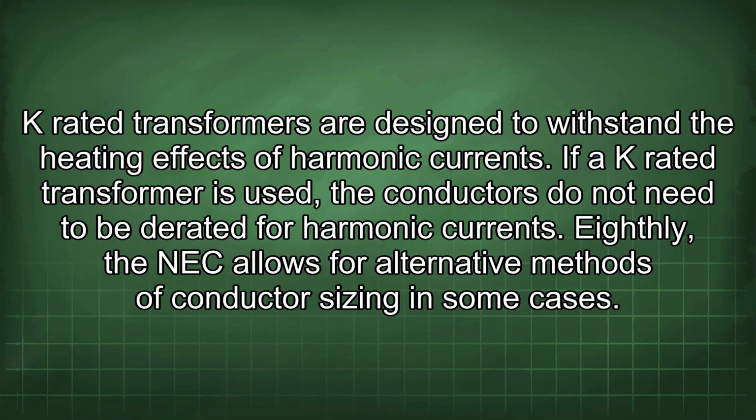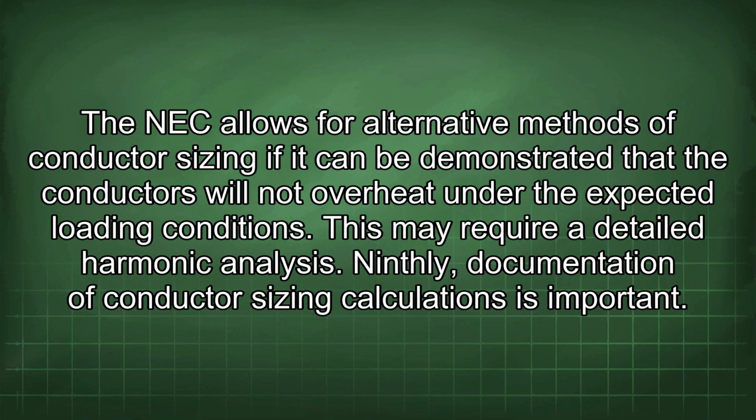Eighthly, the NEC allows for alternative methods of conductor sizing in some cases. The NEC allows for alternative methods of conductor sizing if it can be demonstrated that the conductors will not overheat under the expected loading conditions. This may require a detailed harmonic analysis.